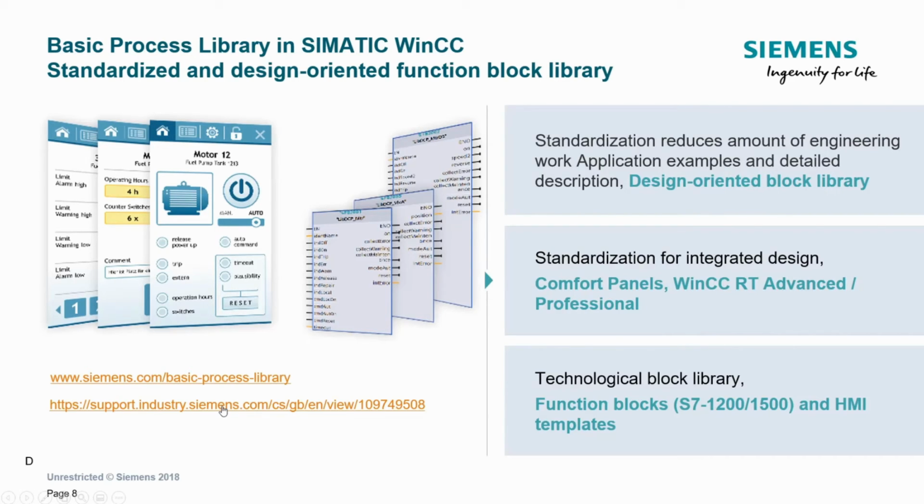Okay, we have designed these nice common look and feel blocks of code, and also interfaces to go along with them. So you can see things there like motors, valves, 3-port valves, Simatic starters, all those sorts of things are all built in, tank controls and all that sort of thing. We've made them for a whole range of things, from the comfort panels through to runtime advanced.